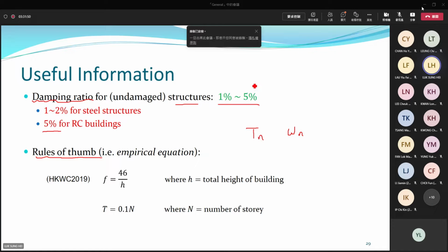But if you want to calculate the period of a tall building, maybe for example 30-story tall, then how to calculate the period or vibration frequency of this system? For a tall building, it's quite difficult to find a single stiffness and single mass, right? If you do not have K, if you do not have M, then you have no chance to calculate omega and T based on our previous discussions.